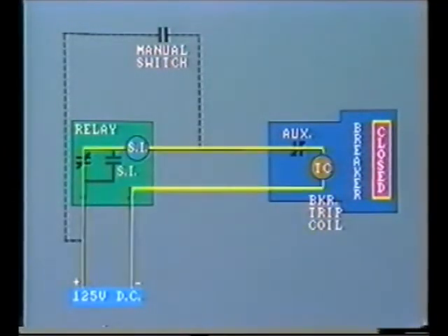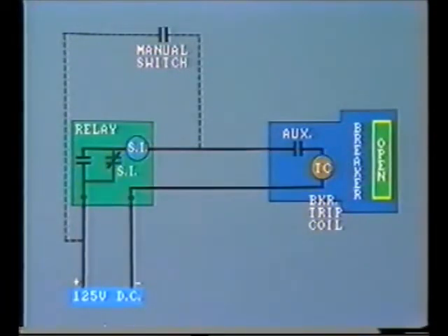When the tripping circuit is energized, the seal-in contactor switch is also energized by the passage of current. This in turn closes the seal-in contacts here, and they will remain closed as long as the circuit remains energized. Now, if the relay contacts open first, they will not interrupt the tripping current, as the closed seal-in contacts provide an alternative path. Only when the breaker auxiliary contact opens will the circuit be de-energized and the seal-in contact also opened.